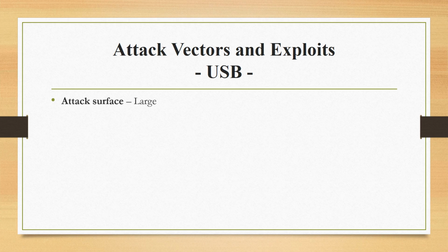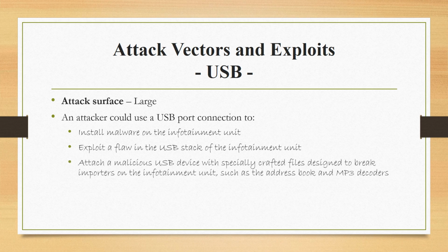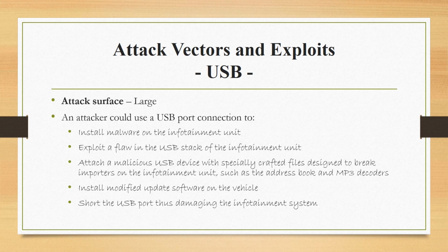USB. Attack surface large. An attacker could use a USB port connection to install malware on the infotainment unit, exploit a flaw in the USB stack of the infotainment unit, attach a malicious USB device with specially crafted files designed to break importers on the infotainment unit, such as the address book and MP3 decoders, install modified update software on the vehicle, short the USB port, thus damaging the infotainment system.